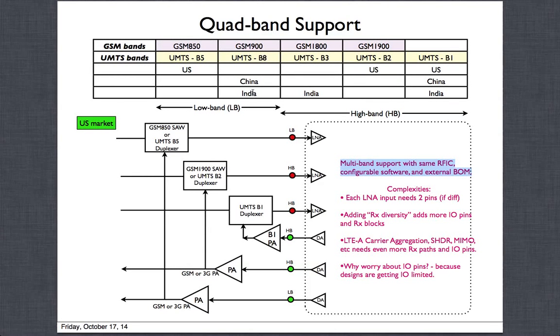If you take an OEM like Samsung, and even the best example is Apple, and I'll tell you a little bit more about them later on, they don't want to maintain different products. They would rather have a single transceiver that they can put in, which can be programmed using software, so you can configure it and change as little as possible in the other components, like the filters and all that stuff. The bottom line is your baseband processor remains the same, your cellular transceiver remains the same, and you can program those. You only change external components like the PAs and filters to adapt to different markets.